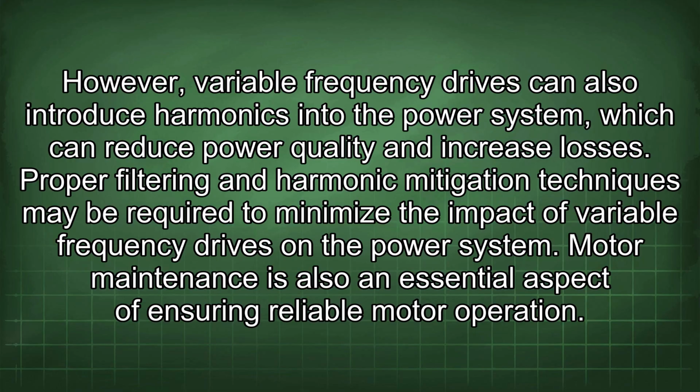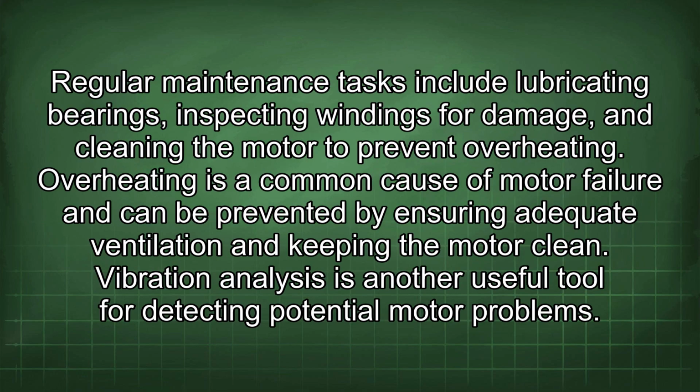Motor maintenance is also an essential aspect of ensuring reliable motor operation. Regular maintenance tasks include lubricating bearings, inspecting windings for damage, and cleaning the motor to prevent overheating. Overheating is a common cause of motor failure and can be prevented by ensuring adequate ventilation and keeping the motor clean. Vibration analysis is another useful tool for detecting potential motor problems.